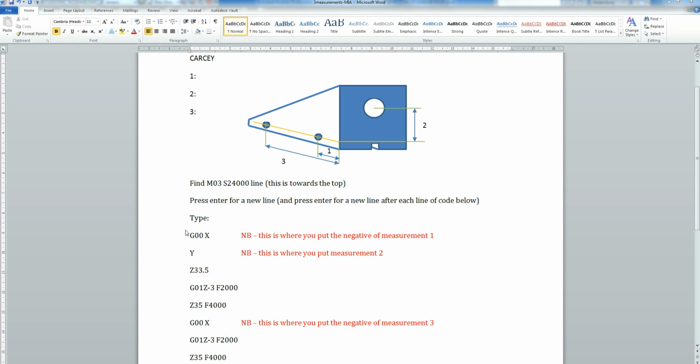Now, this G-code down here, you see, is the same G-code you typed in when you made your very first car. The Z values don't change, but as I said before, we need to change the X values and the Y values. There's 2 X values we've got to change, 1 for each axle, and 1 Y value we've got to change down a certain depth from the canister. So let's find out how to find these values 1, 2, and 3.